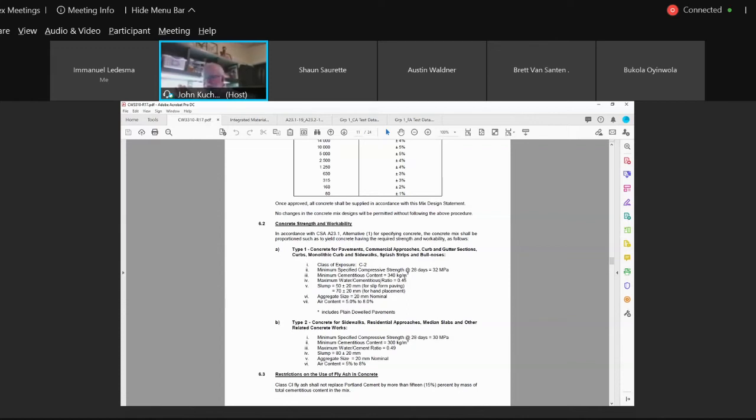It's not. The slump test measures consistency. I can have two 75 millimeter slumps and they'll be different in workability. So how can you say it's a measure of workability? It's not. It's a measure of consistency.